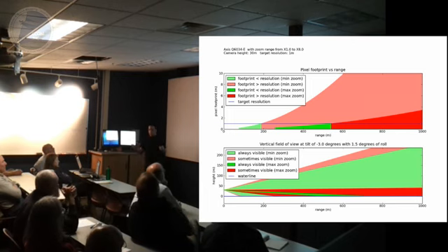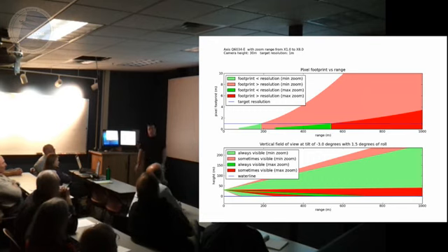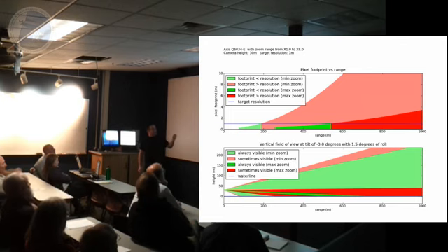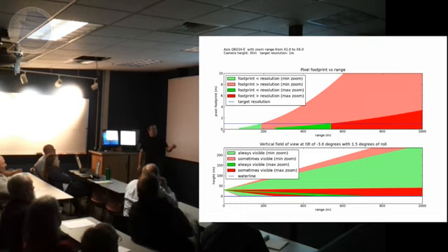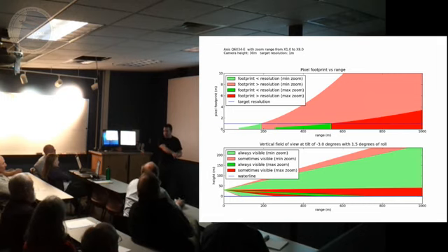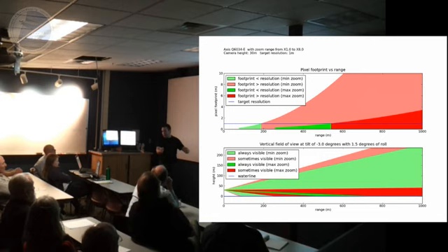It's capable of zooming, and in this case I would zoom from one times zoom to 8 times. So as you zoom in, you bring your field of view down, and I picked the target resolution of 1 meter. And what that means is once you take your pixel and you project it out on the seafloor, what size is it going to be?